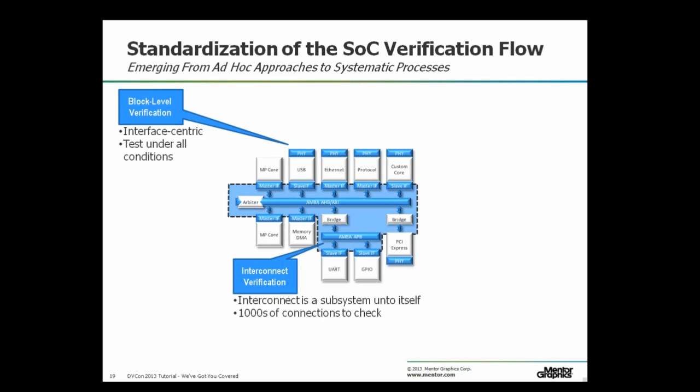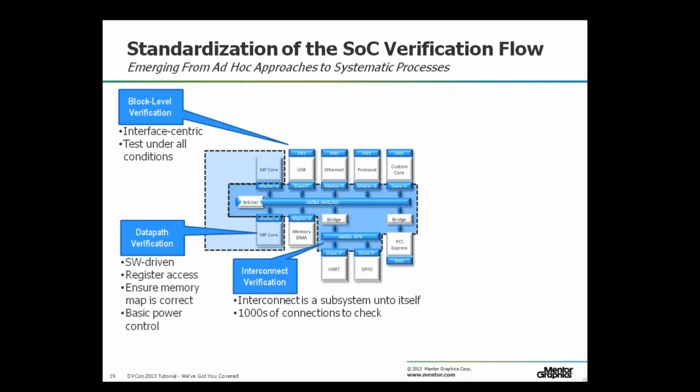But it turns out that there's actually a very interesting subsystem that is sometimes boring, the interconnect, but it's a very complicated and increasingly so complicated subsystem in your SoC designs. Thousands of connections to check, and it's more than just point-to-point verification. Third step is verifying your data path, your registers, your memory map, and some of the basic power control.